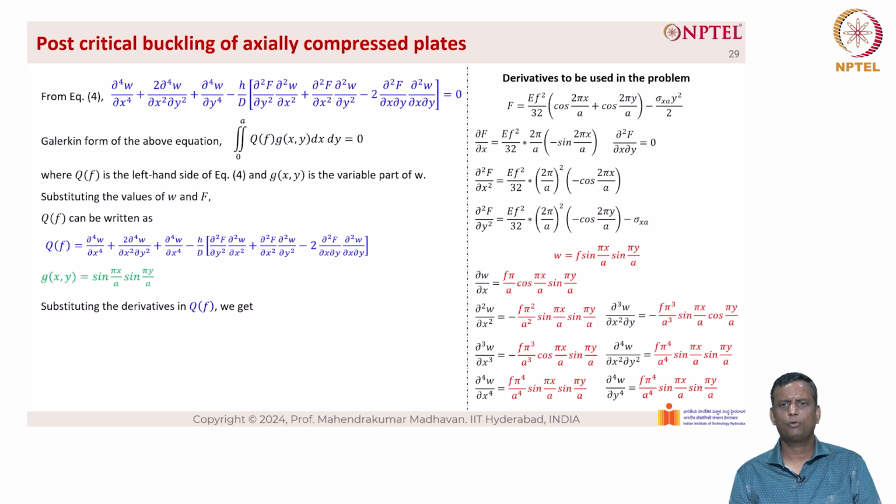So we have ∂⁴w/∂x⁴ equal to f into π⁴/a⁴ into sin(πx/a) into sin(πy/a). And we have ∂⁴w/∂y⁴ equal to f into π⁴/a⁴ into sin(πx/a) into sin(πy/a).